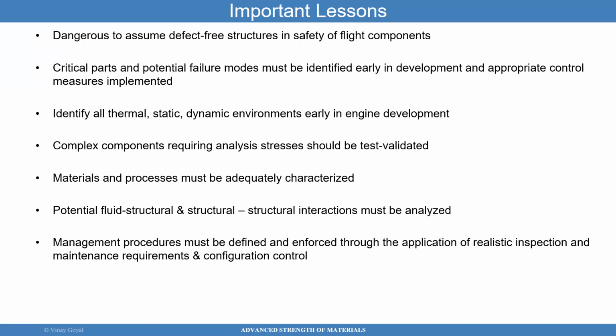So if I'm going to design a diving board for a swimming pool, I want to calculate what is the maximum weight I could experience for that diving board as a designer, and making sure that I design a good diving board that counts for 99.99% of the population. You want to do that study correctly. You do the same thing with an aircraft. You determine what is the envelope of the design and what I need to consider in my design. Materials and processes should be adequately characterized, and a lot of times we forget that there's interactions between the structural discipline and other disciplines.